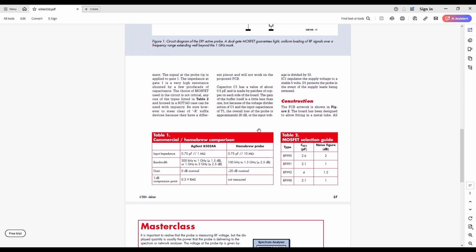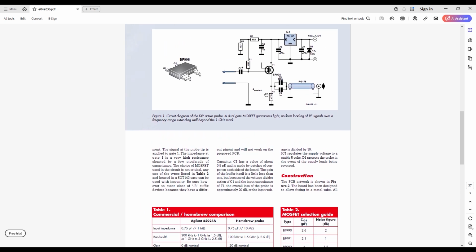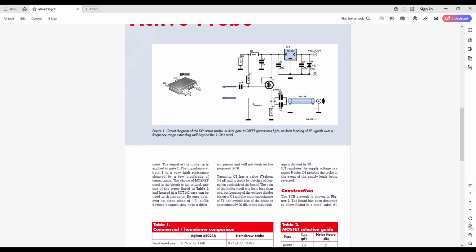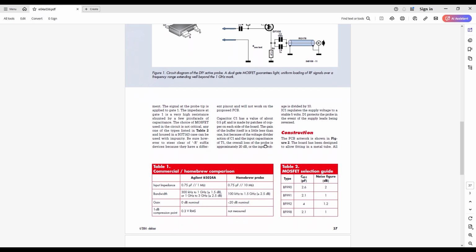Now some disadvantages. The biggest one is the FET itself. 20 years ago when Dave published this design, dual gate FETs were plentiful. But nowadays they've all but vanished from series production. I could not find singletons available through distribution, so I decided to take a flyer and buy 10 of them off eBay. Yikes. Another disadvantage of this design is loss. C1 plus the FET input capacitance and the small loss that you get in a source follower amplifier all adds up to around a 20 dB loss.